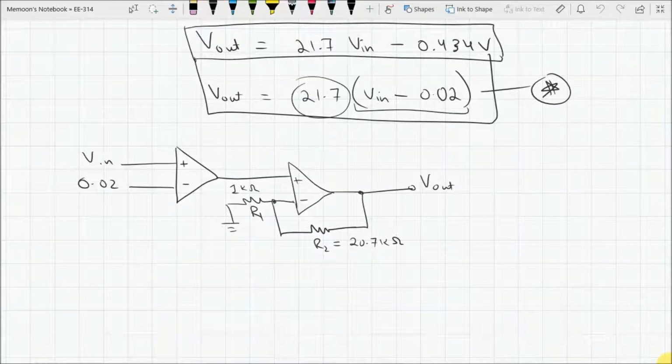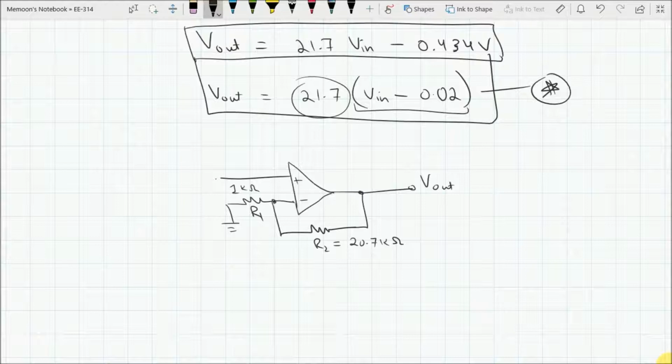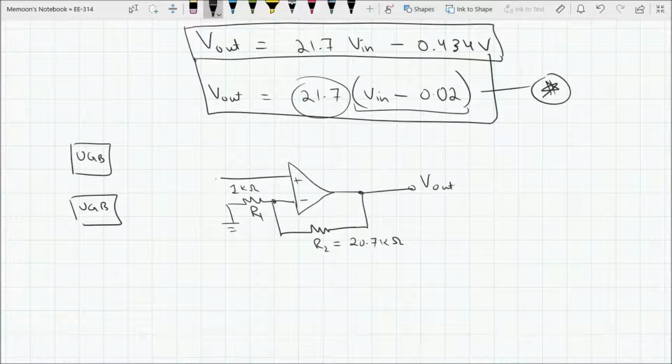So what I'll do is I'll just replace this whole block with a difference amplifier, and a difference amplifier with some buffers. So this is a unity gain buffer, because in case of a difference amplifier we know that there is an effect of loading, and when there is loading on 20 millivolts, it will be further reduced and will result in enormous errors in our reading.